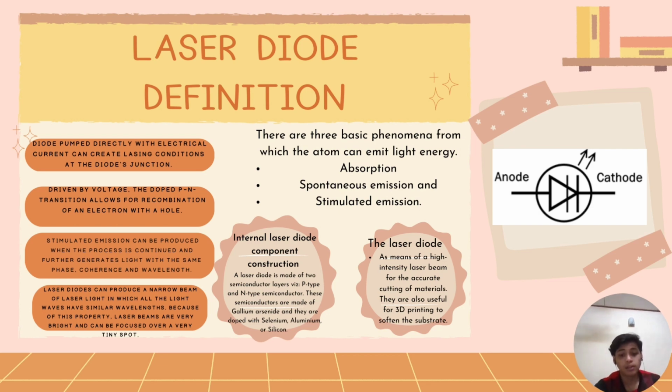A laser diode is composed of a small cavity or resonator that contains the active material, typically a semiconductor crystal or a composite material. The active material is designed to emit light when stimulated by an electrical current. The active material is placed between two mirrors, one of which is partially reflective, and the other is highly reflective. The mirrors are used to form a standing waveform, which causes the light to be amplified and emitted in a single highly collimated beam that is called laser action.